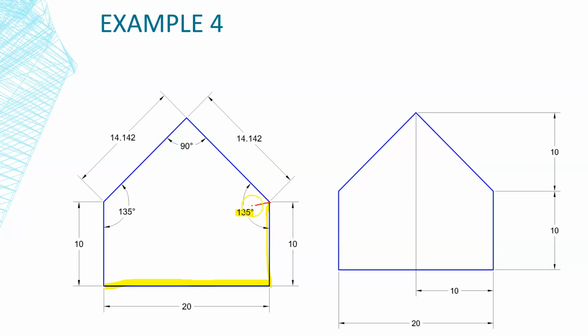If I was to create a line that goes straight across here, you can tell that this angle should be 45 degrees. That leaves this bottom half the dimension that it needs to be, which is going to be 90 at the bottom. That helped me set up what I needed to do on the polar tracking, so that's why you notice that I picked the 45, 135, and so on. So I know that this line is going to go 45 up. And it's the exact same thing on this side.